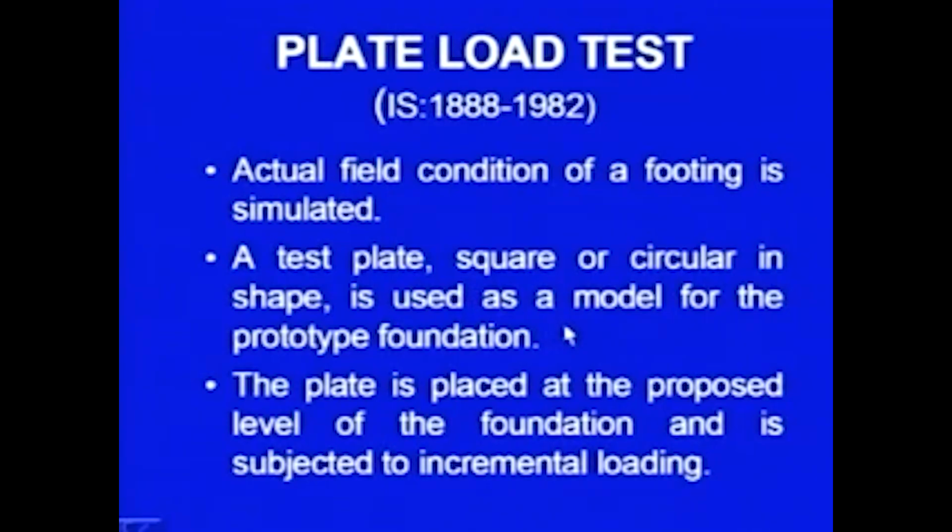So, this was the second test, and now let me come to a very important test, the plate load test. This is a very important test, especially for the sandy soils. As I told you in the beginning, in case of the cohesionless soils, it is very difficult to get undisturbed samples, you cannot get it. So, we have to rely on the field test. So, this is a very important field test for the cohesionless soils.